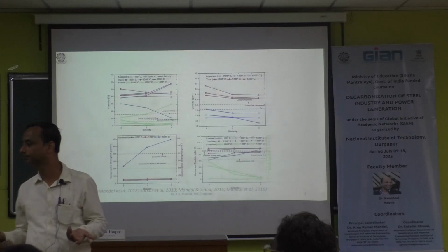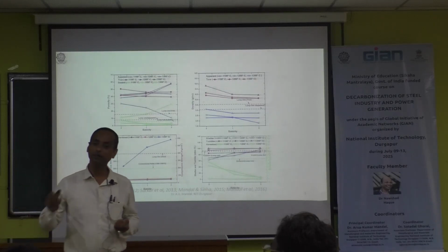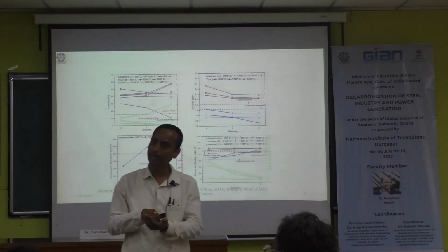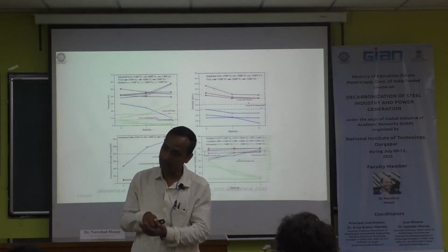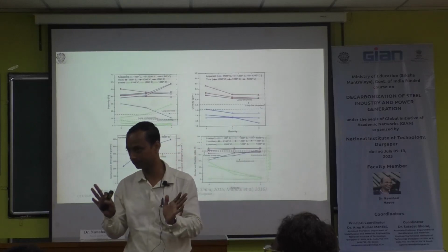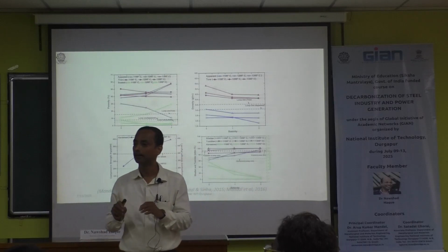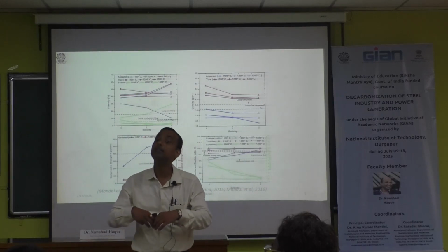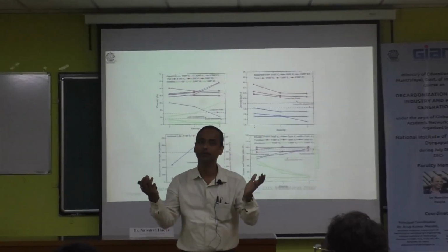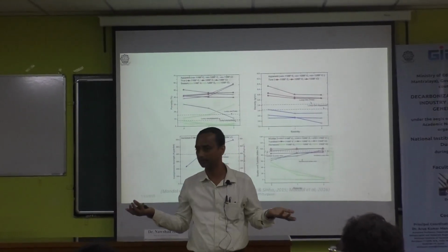Then there are other routes also. You cannot make the pellet by adding limestone, lime fines, iron ore fines, bentonite and water. We have tried it all, because lime in contact with moisture will generate vapor. H2O formation will be there. Steam vapor pressure will break the pellets.